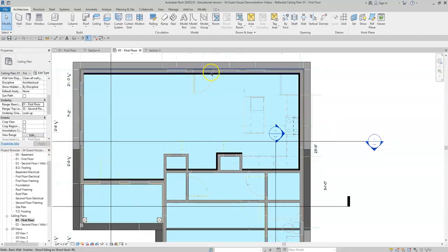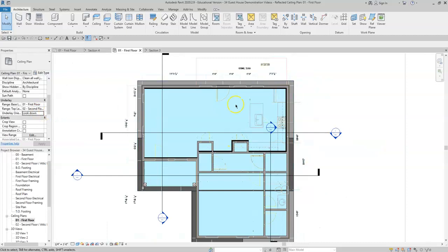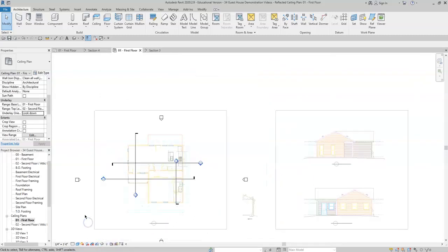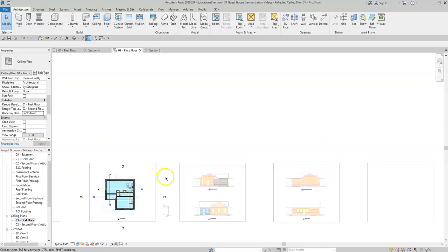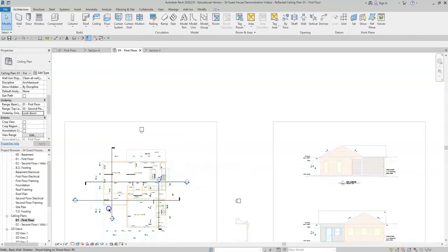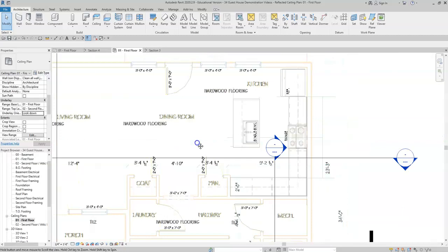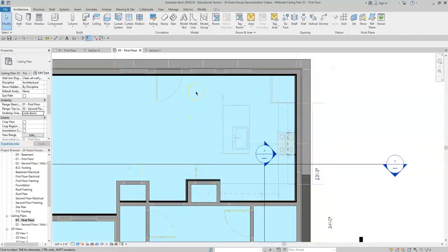we can see things like the windows, the doors. And let's see if I can change this and look down, if that helps us at all. Yes, okay, so you'll change it to look down instead of look up. So that gives us a little bit more with the island area. You still see my superimposed floor plan underneath, but actually I can go ahead and hide that, see if that'll help us. Actually, no, because that's on the first floor. We'll leave it like it is. We're good. So we can use model lines here to draw and find centers of rooms. I would highly recommend that.